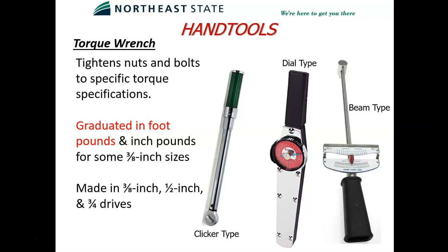We've got a micrometer adjustment on the end, and each manufacturer has a little bit different ways of locking that. So I know like Proto and Snap-on, things like that, right in front of your hand, there's a collar or sleeve that you've got to pull back, and then it'll rotate. And when you release that, it springs back and it locks it in place, and you can't accidentally change it then.